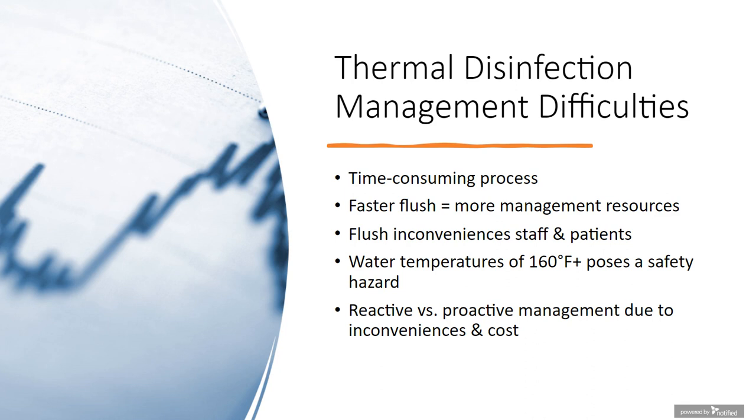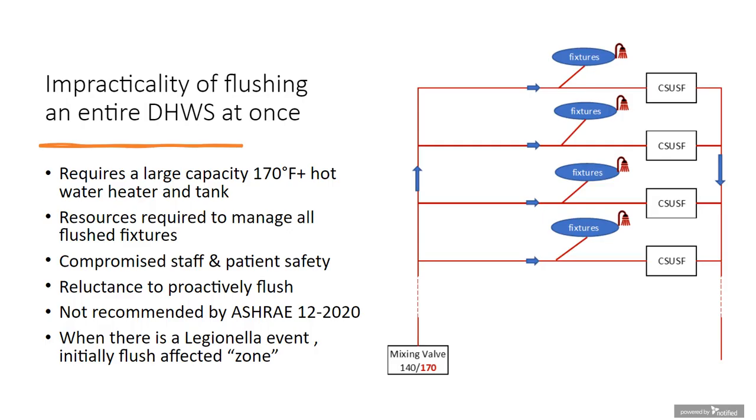Because of the difficulty and the cost of doing this, there tends to be more of a reactive versus a proactive approach to implementing a thermal disinfection process. What that means is, instead of the hospital determining on a periodic basis that they want to do a thermal disinfection, they tend to stay away from it, and they wait until an event happens, unfortunately, where somebody contracts Legionella. Then they go ahead and do some emergency thermal disinfection of those areas that they determine were infected by it.